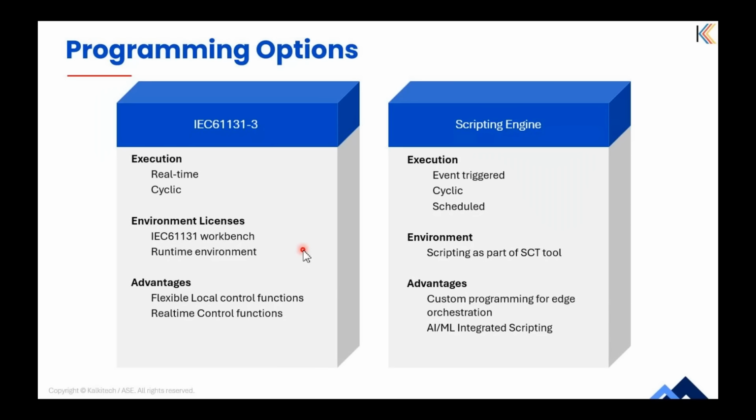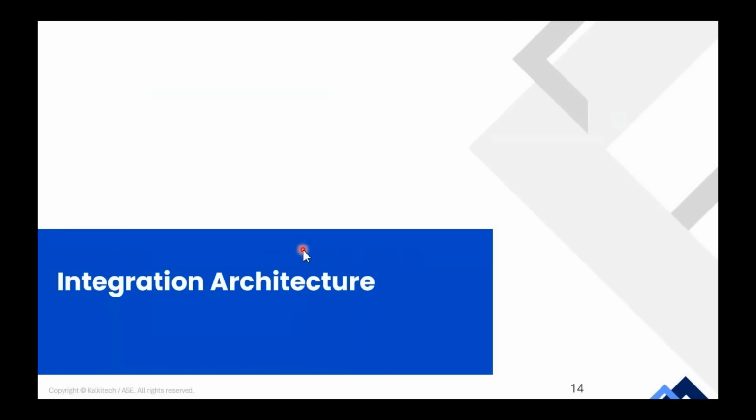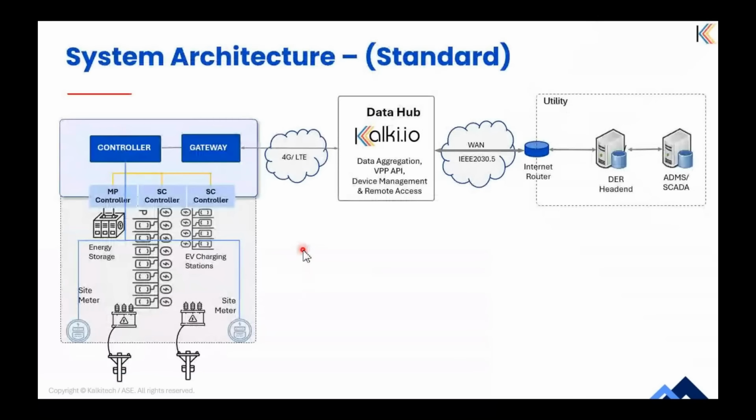We'll go ahead and see the integration architecture in more detail. So there are different integration architectures. This is a standard way, or one of the standard ways, which integration is done with a local DER like energy storage systems or EV charging stations or charging station controller. We have local controllers managing these assets, like a SE controller, the supercharger controller, or a Megapack controller here which manages the battery.